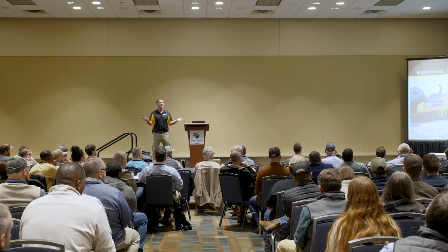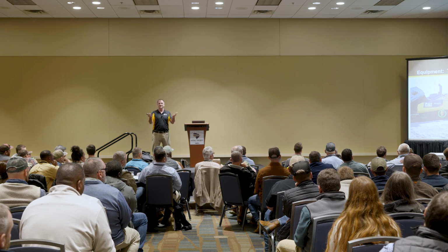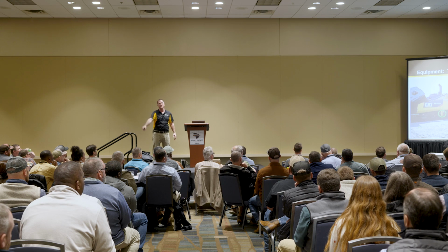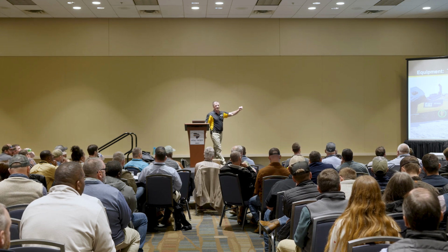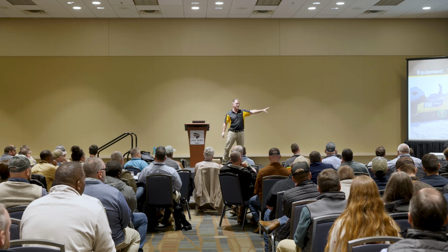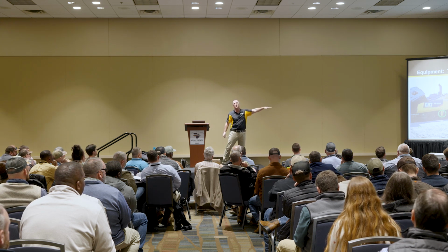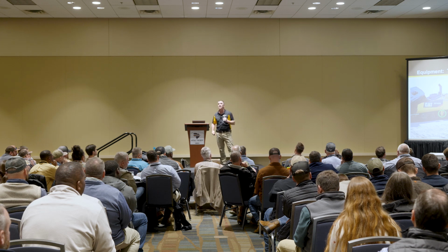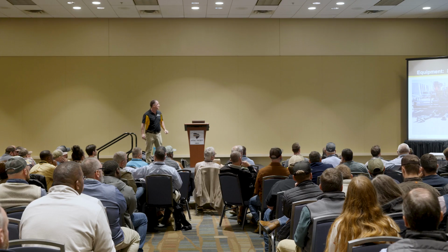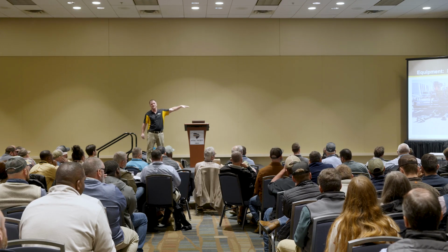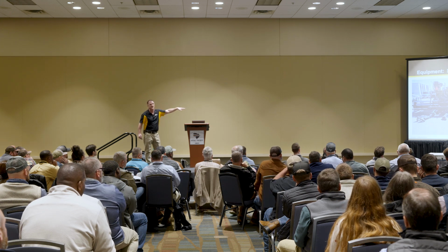So what's the only thing holding that screed up when I'm paving? The material underneath, exactly. It's that mix going underneath it. I'll come back to it a bit, but that head of material, or that amount of mix in front of the screed, is going to affect how the screed rides and what our final grade and slope comes out as. When we look at the equipment, I've got 4 guys underneath that screed taking a look at it. Probably shouldn't have him in there because he doesn't have a hard hat on, but I don't think that's going to help if something bad happens. But don't get under a screed unless you've got it blocked. Safety, which these guys do.